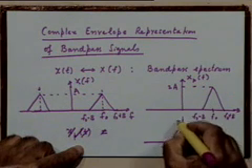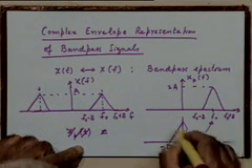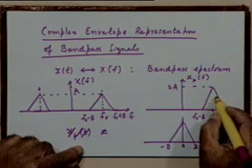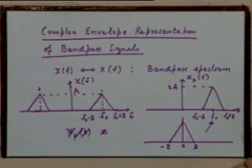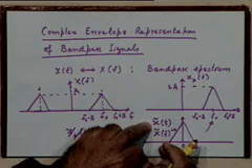So all I am saying is there is a frequency translation relationship between this signal that I am defining here and the signal xpf, which is the analytic representation of our original bandpass signal. Are you with me, everyone? Now, how do I represent this mathematically? If I call this signal x tilde t, of course this is the spectrum, so what I am plotting here is not x tilde t but x tilde f. This is a plot of x tilde f, and the corresponding time domain signal I am calling x tilde t.